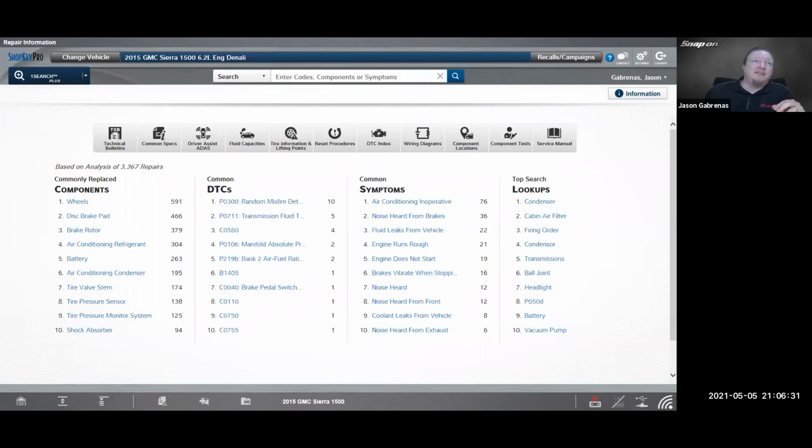Let's see. Anonymous attendee asks, so each of the data packets can contain different data for their corresponding controller? Yes. So let's say the engine controller is sending out engine speed, and the ABS controller will send out wheel speed, and the engine controller sends out something else. So it's going to send out packets of data, bunches of data at the same time, just kind of in bursts. And then whatever module needs that data, say the transmission controller needs input from the engine controller as to what the RPM is, the load, the throttle position, it would take what it needs and then it just uses it that way. Hopefully that answers your question there.